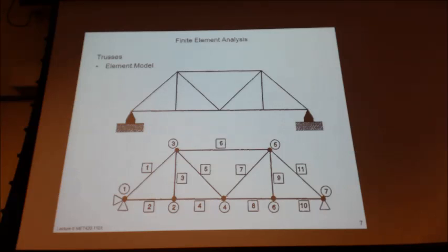Anytime we can take advantage of symmetry, then we may as well. Saves you time to put the model together, saves you time of processing, but we have to be a little careful about how we do that and be cautious in setting up our constraints and loads.